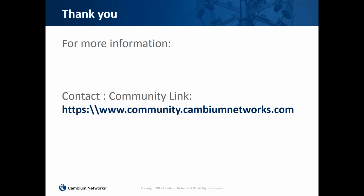Yes, so in terms of whichever method of synchronization we use and whichever product you use, the synchronization will be equivalent. So you could have a mixed network of 670 or 650 using PTP sync. You can introduce on the same network 670 using either PTP sync, either HCMP or Cambium sync. The synchronization is effectively equivalent. So whichever method you use or whichever product you use, they will all be synchronized properly.